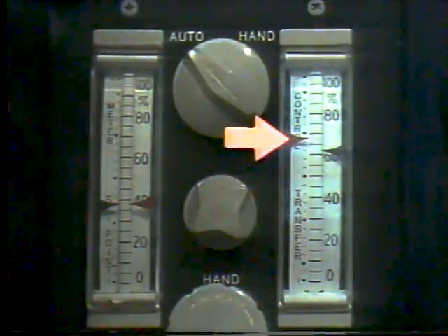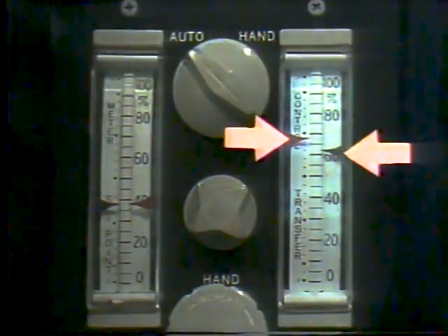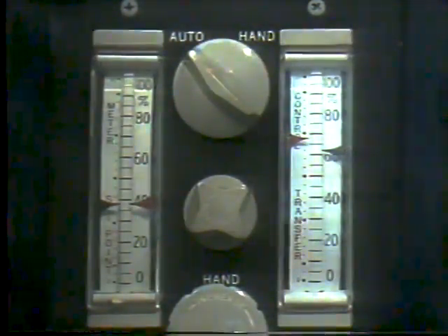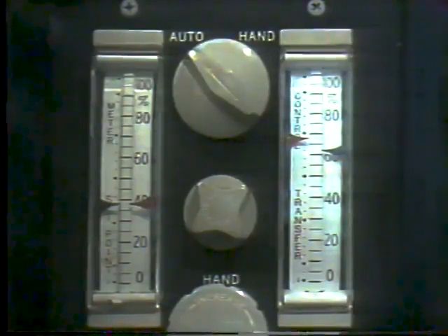If the transfer signal is not matched with the controller's output before the switch, the controller's output will change when the selector is switched. The change will cause the final control element to momentarily move. This will appear as an undesired bump in the reaction curve. When the transfer signal is properly matched with the controller output signal, the bump will not occur. This is known as a bumpless transfer. Making bumpless transfers saves time by eliminating undesired changes in the process.